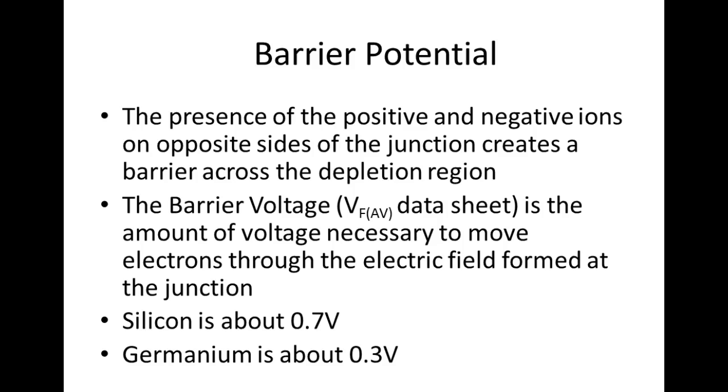So how do we compensate for that? We put a diode in series, forward biased. When it dropped that 0.7 of a volt, it went back down to 3 volts, and now the thing worked okay. What was nice about our flashlights is they were rechargeable. So instead of trying to get batteries all the time, every night before we left we'd hook them up to our chargers. The next day we'd come in, plug them in, and have a real nice flashlight that wouldn't blow when you dropped it. So that's just the 0.7 of a volt of silicon.